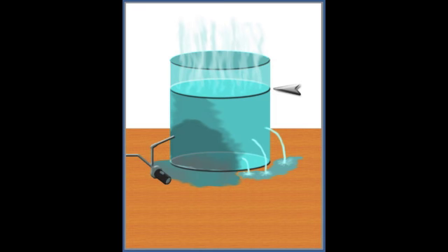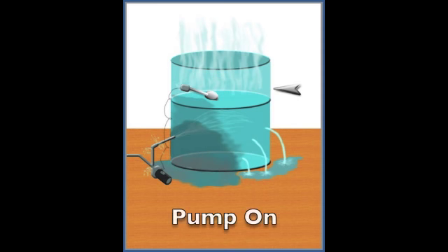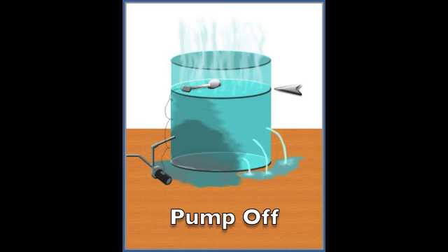The pump represents a furnace and the pipes represent the ducts. A furnace is simply a BTU pump that adds BTUs to the house as they are lost. The float switch represents a thermostat, which is really nothing more than a float switch measuring levels of BTUs in the house. Just like a float switch, it only has two modes: on and off. Determining the leaks in the tank and selecting a pump is analogous to doing heating load calculations and selecting a furnace.